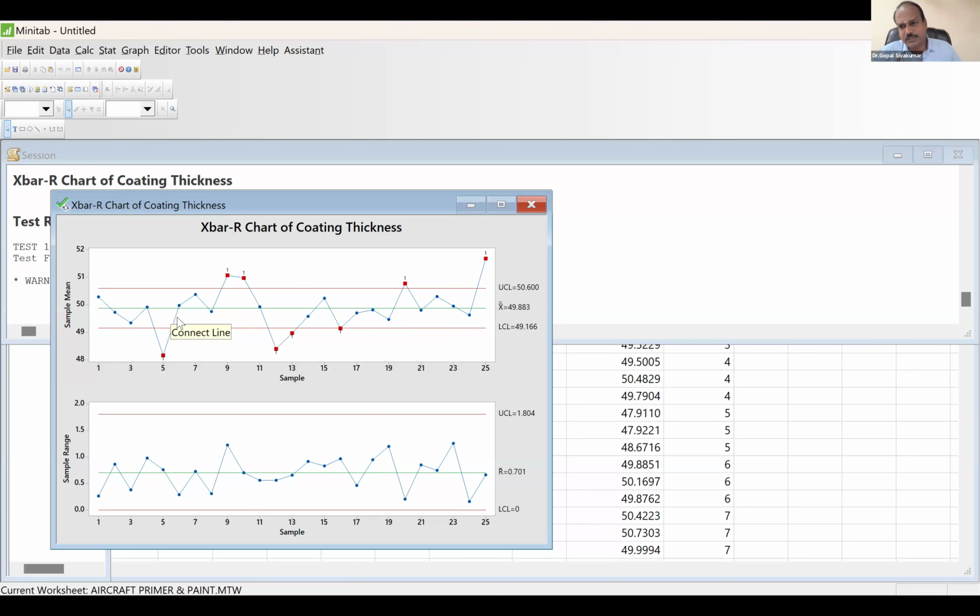All of you understand what we are doing here with the Cpk, Ppk and control charts? All the tools are for your decision making. They're all available. But how you use the tools is in your hand. Many people simply look at Cpk and come back. They don't look at the control chart. But some people like you can look at Cpk, also the control chart, also ask for the action taken report, also go for personal sampling.